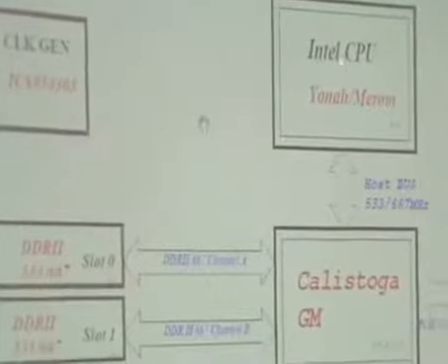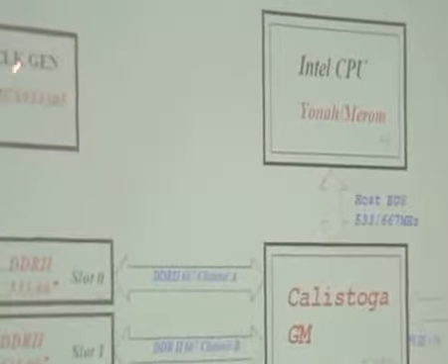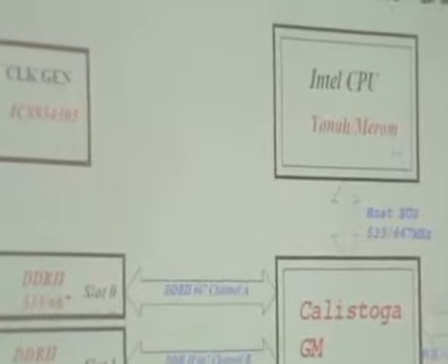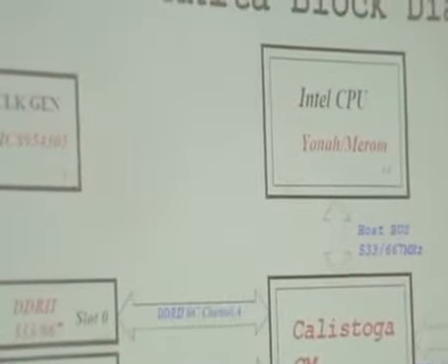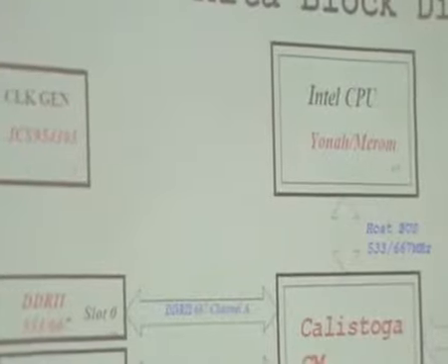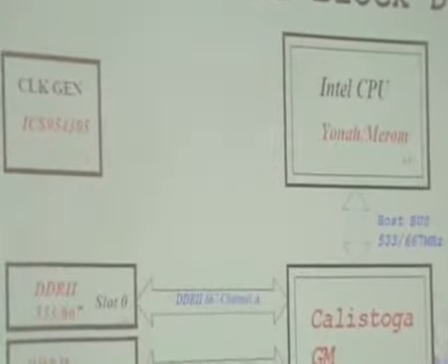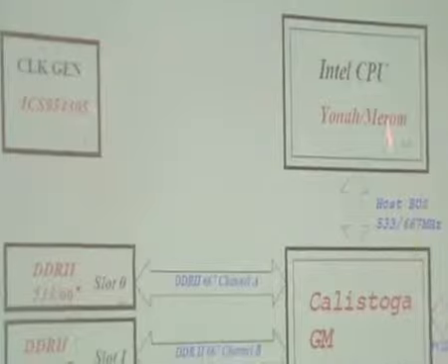If the data has to flow at such high speed, then the wires will radiate and act as an antenna. The two wires will act as an antenna, and the data won't reach the connectors. So we have devised a lower speed, called the FSB speed. So this CPU will issue a signal to the clock generator telling it my front side speed is this. Then this clock generator will give a return signal to the CPU: okay, this is your FSB.